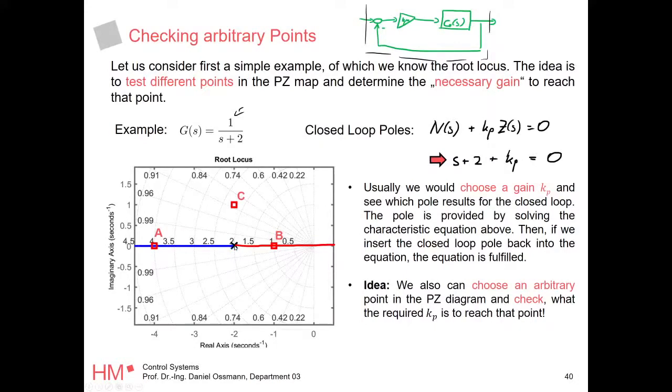We're making it faster, we're making it better, so to say, in terms of stability and performance. We are moving that guy to the left. The time constant gets lower. We are moving away from the area of instability. If we do positive feedback, we are making our situation worse. We are moving towards the area of instability. Here, we are making our system slower.